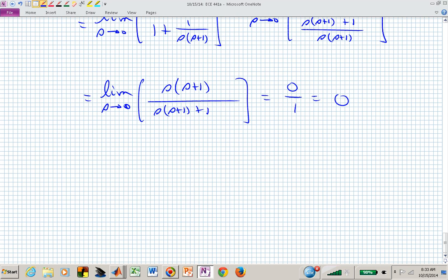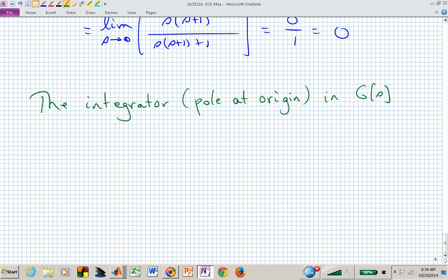Is that correct? You guys said this would have the worst steady state accuracy in the last lecture, I think, because it was the slowest, wasn't it? It's hard to remember back to Wednesday, or Monday, but this integrator in our open loop system, or the pole at the origin, that integrator in g of s is helping to drive the error.